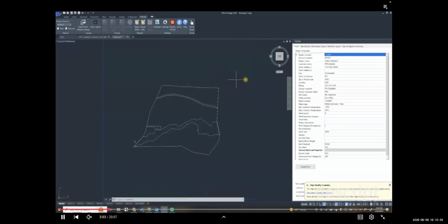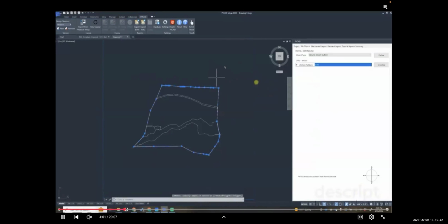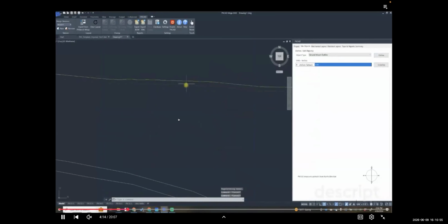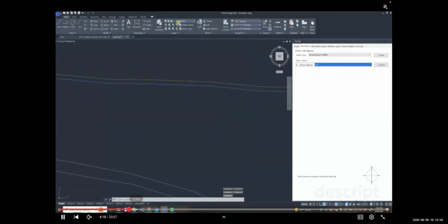properties here. So basically you define what is the outline of the parcel. You define all the obstacles that are in the layout. So you see now, basically, you can adjust, add setback either individually, or let's say a uniform setback that you can adjust for the land parcel, and then also add different obstacles, and you can define them as obstacles there.